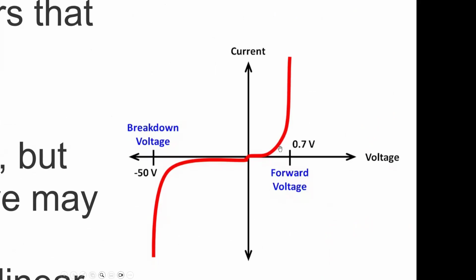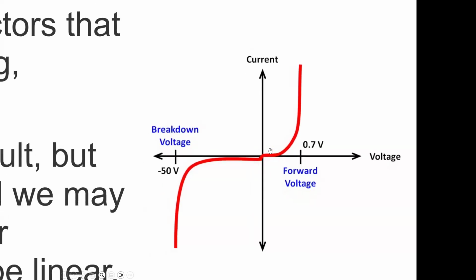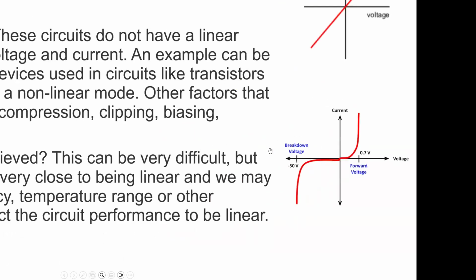Then you might design the circuit and the component inside that circuit so that you use that part of the curve that almost looks like a straight line. Of course, we're not doing this with diodes because the change is happening just too rapidly. But with transistors, we can.